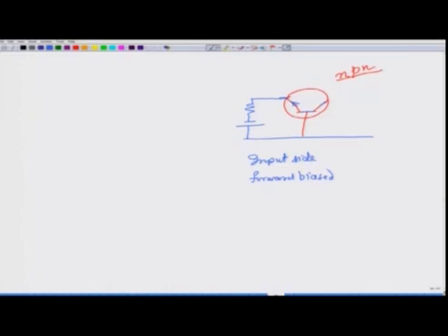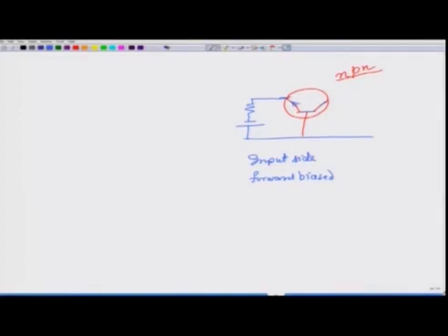On the other side, the collector side, this should be reverse biased in normal operations. So, I am drawing this circuit for most of the applications which use this kind of situation. Now, you have this junction here between this collector and this base. This junction should be reverse biased. Remember, it is NPN. So, this side is N and this side is P, and this should be reverse biased. So, the N side should be connected to the positive of the battery. So, your battery will be like positive here and negative here.